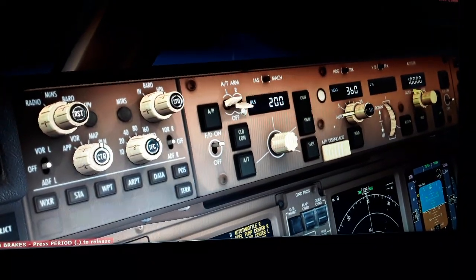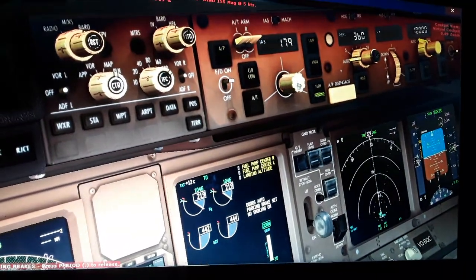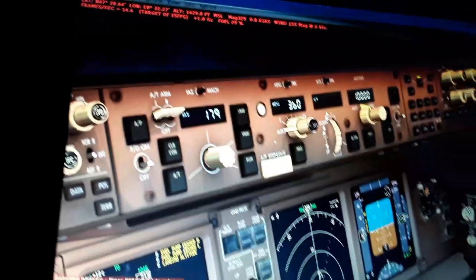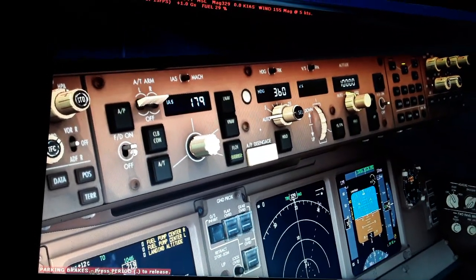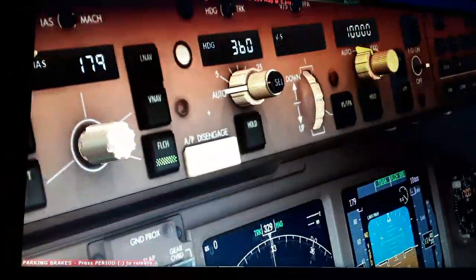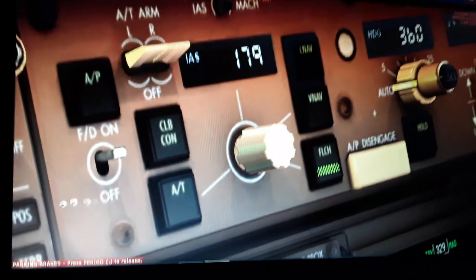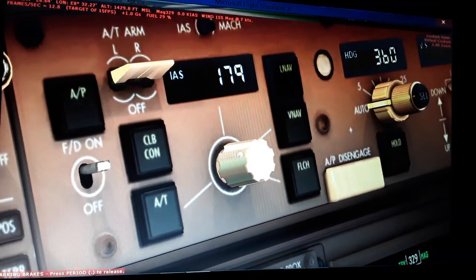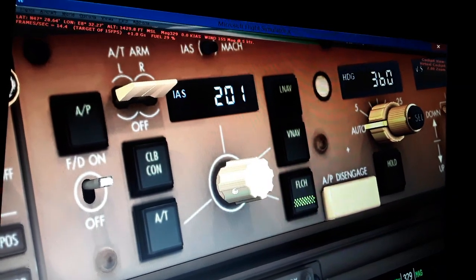The flight director. So you can use the flight director on and off to switch off a mode to reset. So if you turn on the flight level switch, you can turn off the flight level switch like this by turning off the flight director. It turns off this as armed mode. You can also use to turn the airspeed.